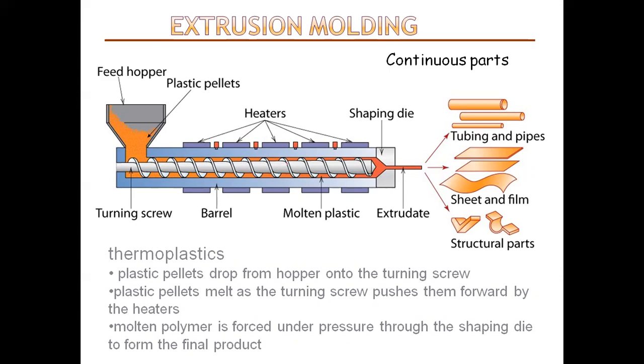Okay, so whatever extra heat there is, is contributed by the intense pressure and friction taking place inside the barrel. In fact, if an extrusion line is running certain materials fast enough, the heater can be shut off and the melt temperature can be maintained by pressure and friction alone inside the barrel. In most extruders, cooling fans are present to maintain the temperature.